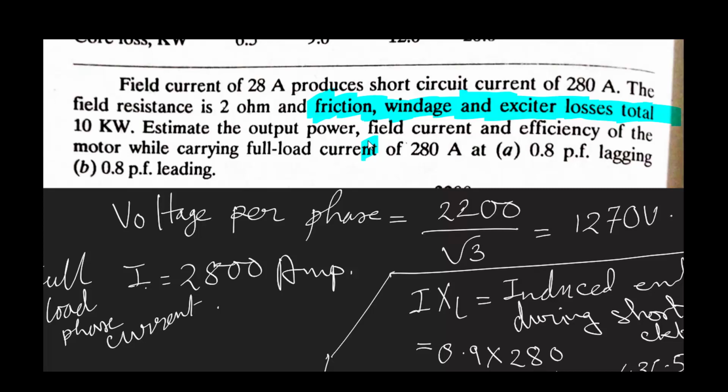Here in an induction machine, what happens when you load your machine is that it slows down, which means your machine speed goes down. Suppose at no load your machine, say a 4-pole machine on a 50 hertz supply, has a synchronous speed of 1500 rpm. At no load the machine was running at 1495 rpm. Very good.